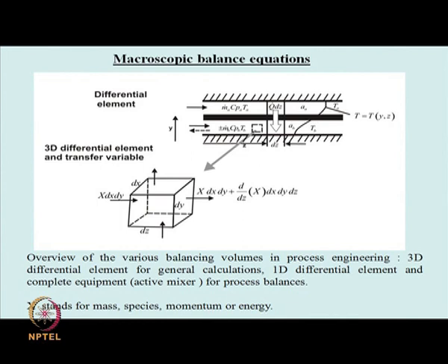This is the solid boundary, and you have another fluid, a cold fluid, which is moving in the other direction, and then you have heat transfer across this from the hot to the cold. So, you can take a control volume, defined by certain distance, and therefore, find out what is the total heat that is being added to such a system. If we can think that it is just a 1D process, then it's simple, we can take a 1D differential element and make such balances.